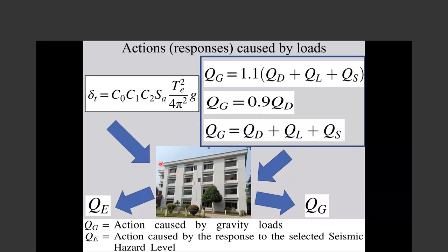We ask the software to use this lateral load distribution, and we assign the number of steps. Then the software, step by step, increases the load and does the analysis, increases the load and does the analysis, till the maximum top displacement reaches the target displacement. If it doesn't reach it, we make sure that it's not a numerical problem. If there is no numerical problem, we say that unfortunately the building can't undergo this level of earthquake.